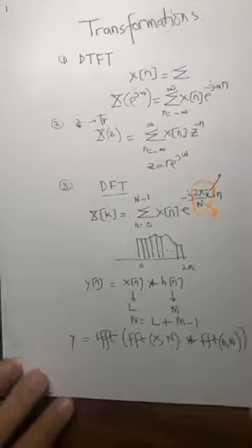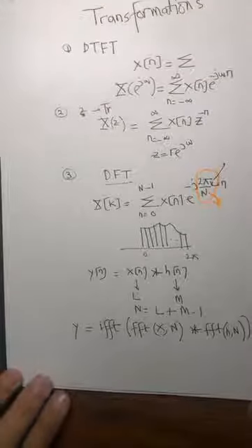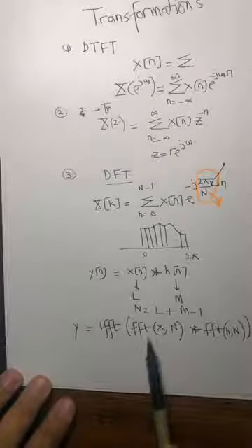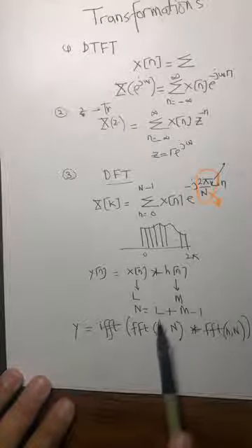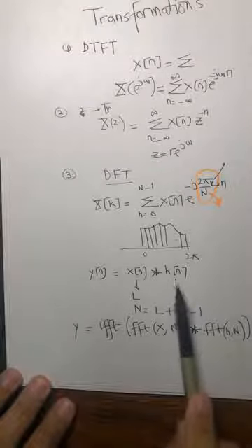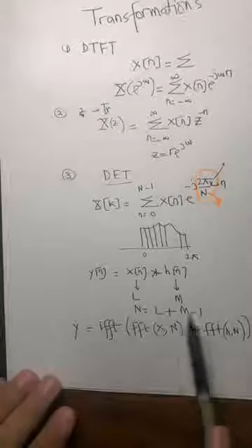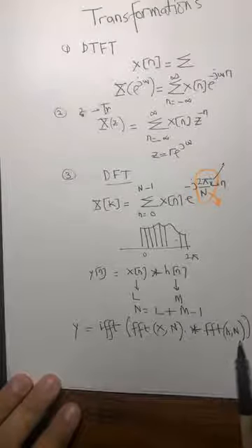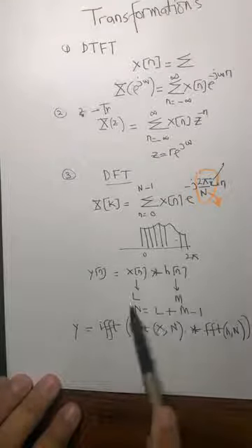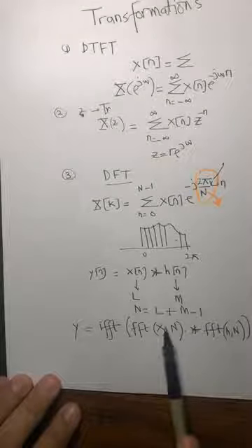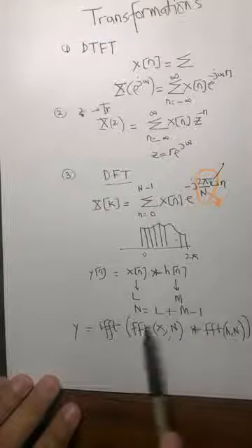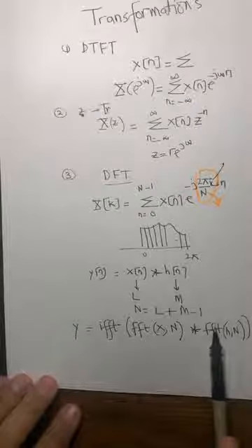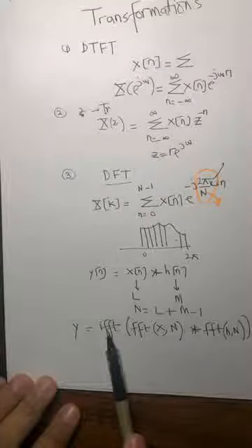So convolution, even in real systems, can be implemented using a convolution summation, and many a time this is also an effective way of finding convolution. Because h is a filter that you have designed, you have to take its Fourier transform only once, an N point Fourier transform. The data you collect is L samples, so you zero pad it to make it equal to N, then you take the FFT, do a sample by sample multiplication, and then take the inverse fast Fourier transform.